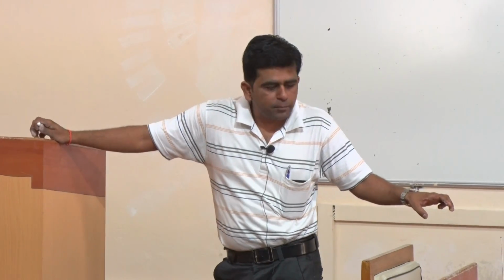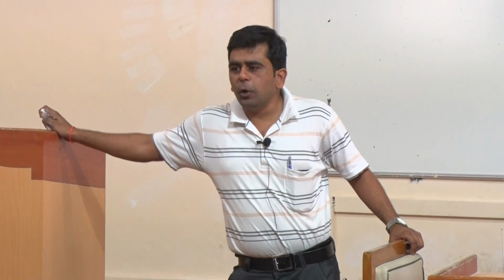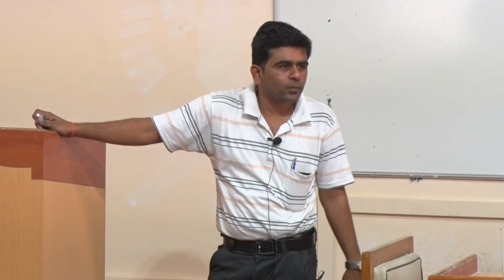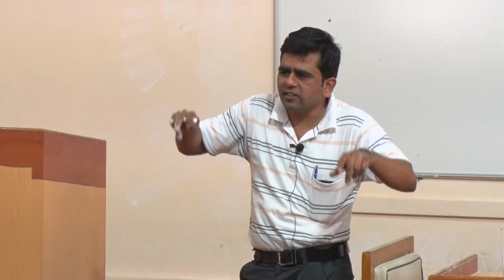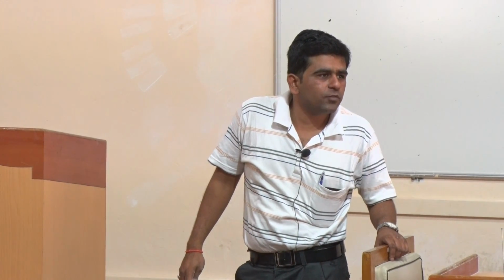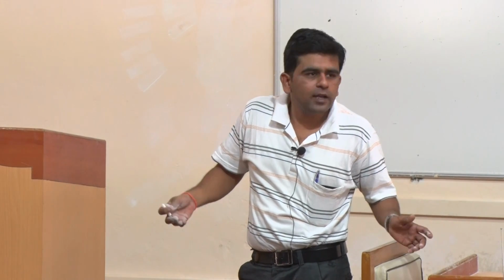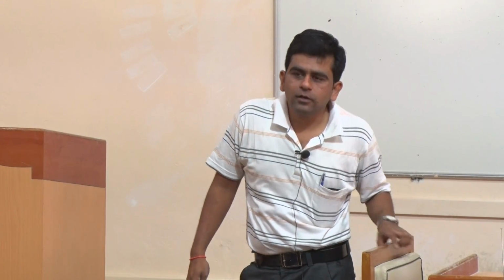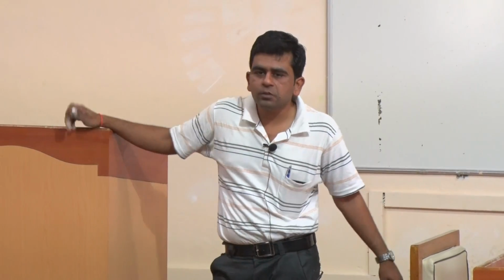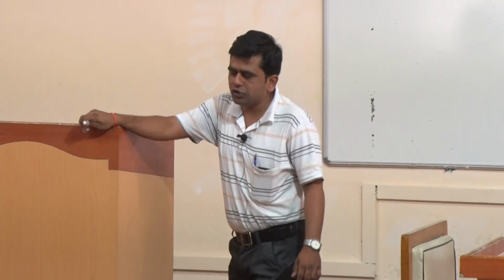Here we have made one assumption, that whatever the input to the matched filter, it is known to us. When we are using the PCM, yes, we know what is the input to your matched filter. Is it rectangular pulses? Yes or no? For digital communication systems, where we are using any delta modulator, DPCM, any one, here we know what is the input to your filter. Here the main point is the matched filter gives the maximum output signal to noise ratio provided the signal is known. Right, on this point, the matched filter gives maximum signal to noise ratio for a known signal.